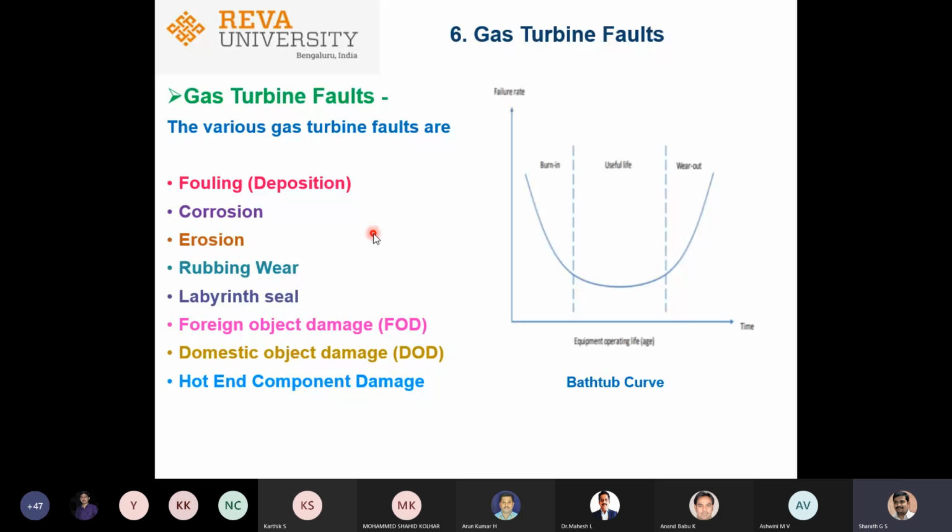Someone has to go inside the air intakes and check for any deposition of sand, dust, dirt, or carbon deposits. Even slight deposition of carbon will have a tremendous impact on the performance of the engine, and it becomes very critical from a military perspective when you are not able to have the required thrust that is set by the OEM.